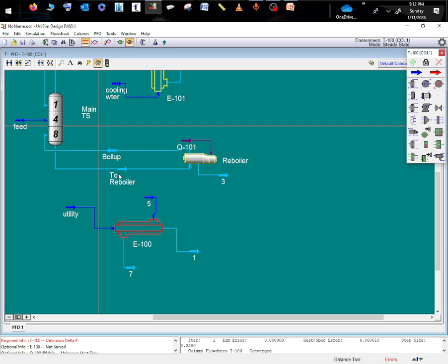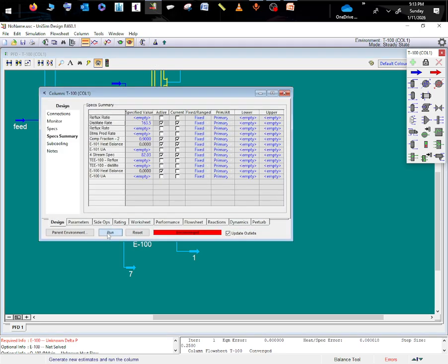And so we further analyzed and we saw that the reboiler acts as another stage. So it's actually an additional stage because in the top part we had a total condenser, so there was no need for a two-phase separator. It was a total condenser, so we had one phase. Now, let me just show you something real quick. Okay, just before that I'm going to deactivate this heat balance added automatically after adding the heat exchanger.